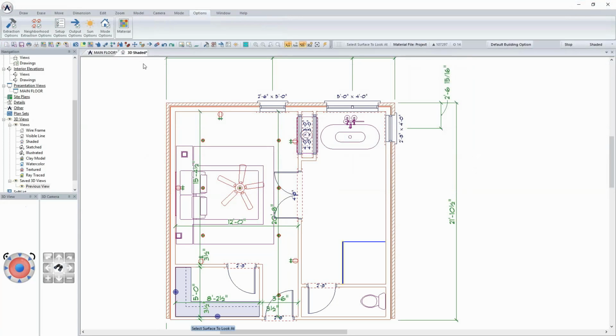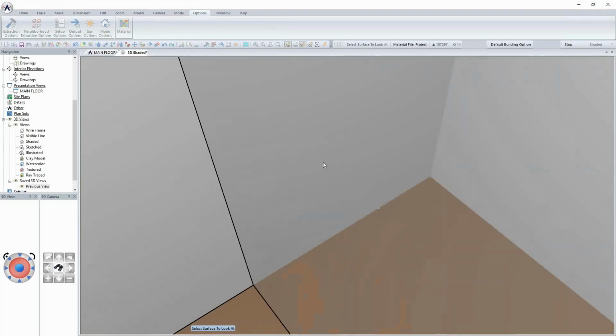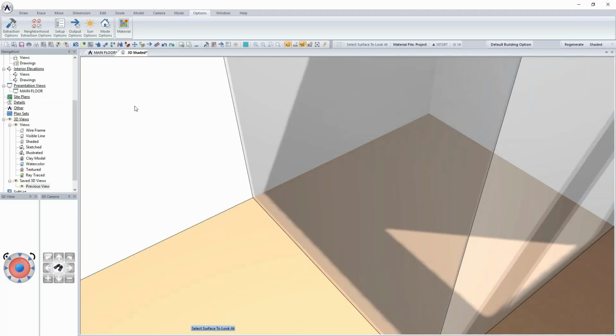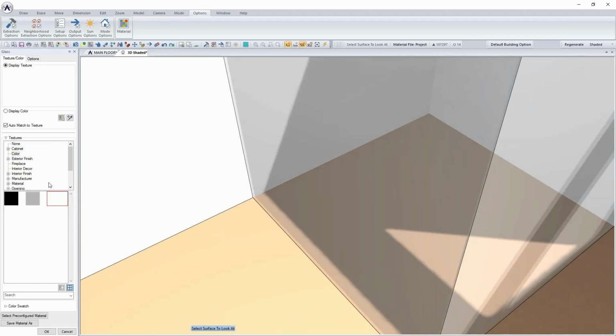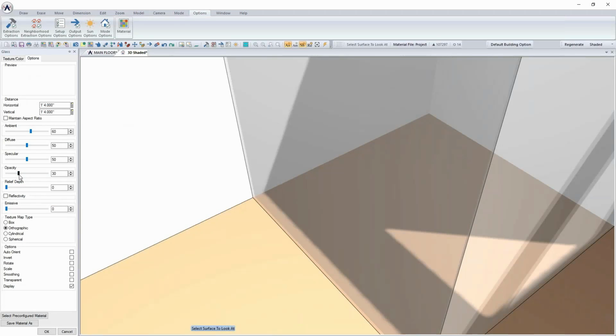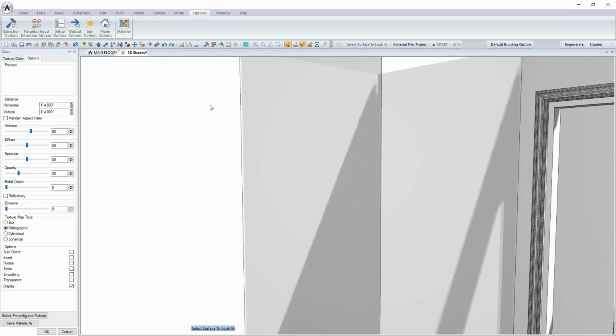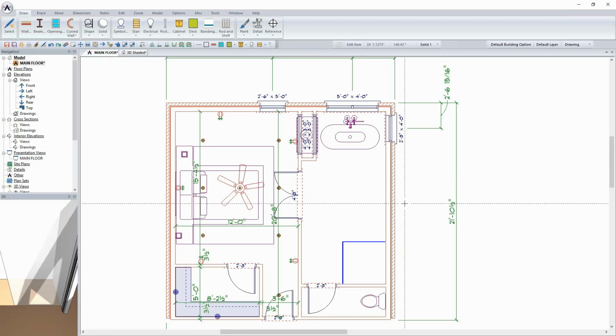When you take a look at this inside the 3D, okay, as we zoom back out and in, all right, as I take a look and do a surface edit on this, it's literally just defined as having a white glass material. And as we take a look at the options, it's going to have an opacity of 30%, which means that it's 70% transparent. That's why we can see through onto the other side of the wall. Okay, and in time we'll probably turn on reflectivities and so on so that we can actually see through the actual plan.